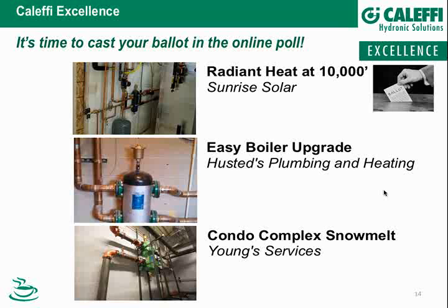Delta P, I tend to like Delta P with valve-based zoning because it's an instant response. There's really no sensors involved in that. It's independent of outdoor reset control situations. But again, I want to stress there are good applications for both of those. And I think we're going to be talking about that more.